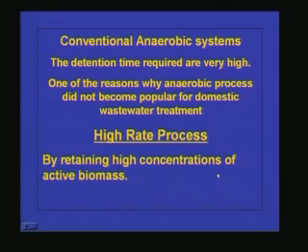Another reason is the sludge production. In the anaerobic process, we have seen that the organic matter used for anabolism or cell synthesis is less than 10%, whereas in the aerobic process it is around 40 to 60%. So definitely the sludge produced in the anaerobic process is much less compared to the aerobic process. So sludge handling is not a problem at all. Moreover, the sludge generated in the anaerobic process is almost mineralized. So we do not have to go for any further treatment; we can directly put it into sludge drying beds.